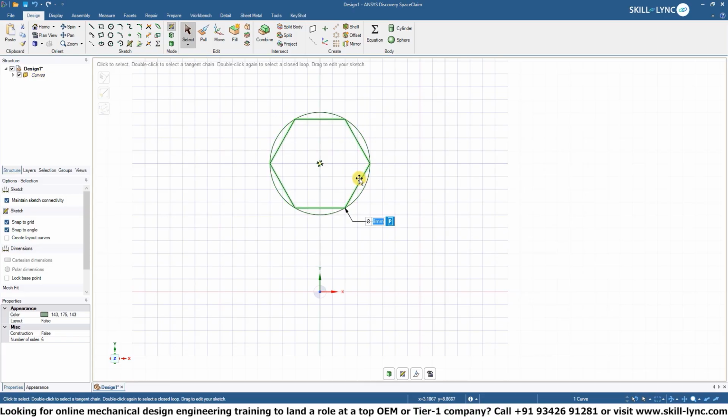I was having a bit of difficulty because, as I mentioned previously, when you draw different intersecting geometry, intersecting lines and whatnot, certain relations are held between the geometry. So over here, these points of the polygon are now coincident with the circle. So when you edit something, it would generally try to edit it all together. Now it's not doing it. It was doing it previously. That was interfering with my demonstration. But that's something that happens sometimes, regardless of your experience.